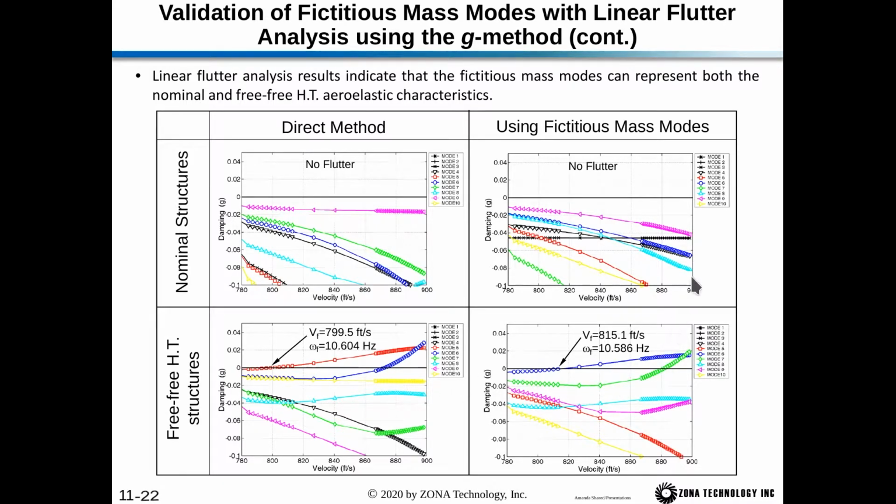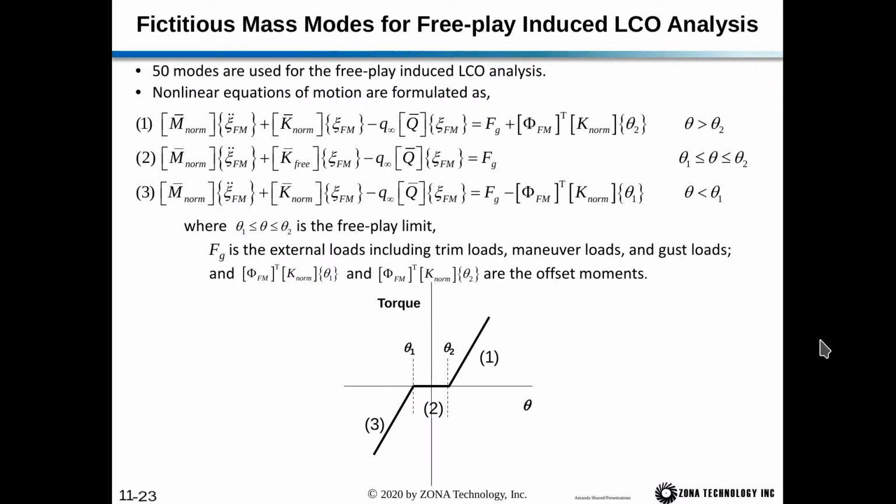So this means that we can use the one set of mode shapes to represent both structures, which is needed because in the nonlinear flutter model, we have to stay with the same consistent set of modes. We can't switch modal basis in the middle of the time simulation. So next we'll build up the nonlinear system.